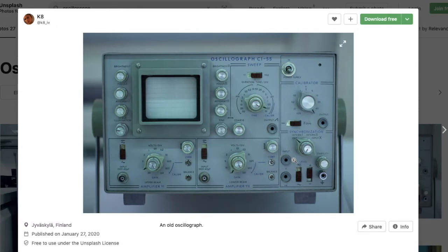If we look at any oscilloscope, its interface must have a screen where we can view the voltage versus time graph of the input signal, the ports where we are going to feed the signal, and some knobs to change various settings like the time scale or time per division scale and the voltage scale. Here, notice that we can vary the voltage per division settings of each input. Here we have input 1 and input 2, therefore we can also simultaneously vary their scales using this voltage per division knob and this second voltage per division knob.